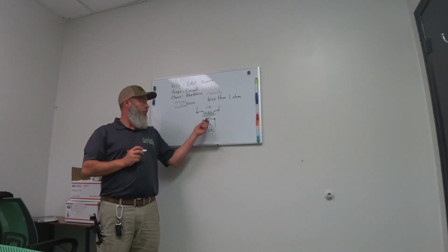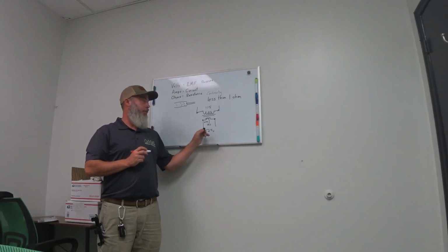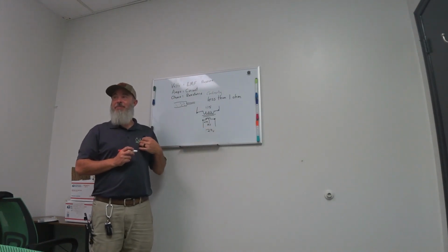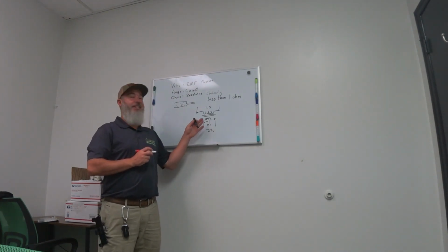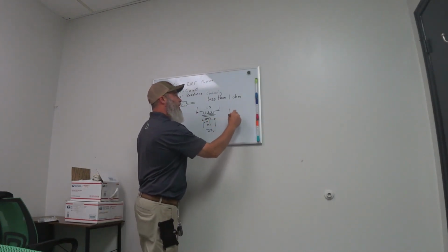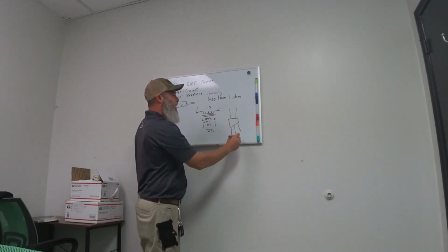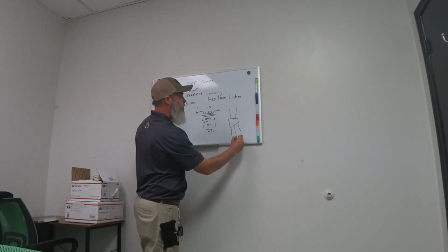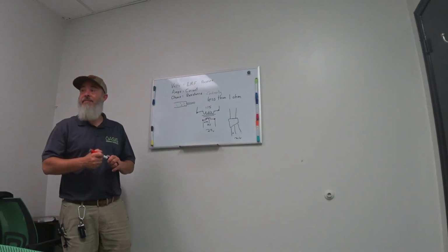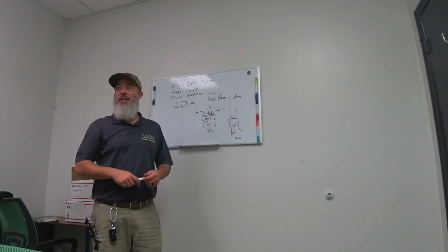Anywhere in that coil, you could put a tap and get anywhere between 0 to 24 volts. Now, we don't put those taps in there. Instead, this is a transformer that's going to come like a box. It's going to have 2 wires in for 115 volt, 1 wire out, and 3 wires out. From here to here is going to be 24. From here to here is going to be 10. It's probably going to even have a connector on it, so all you do is just plug it in to the board.